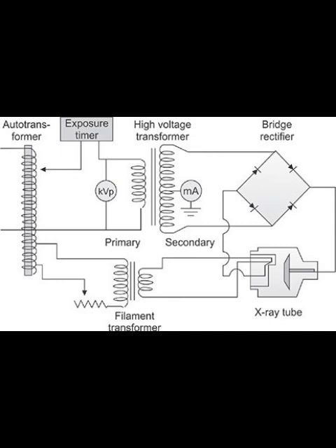It is. Voltage ripple is basically the fluctuation, the variation in the voltage output after rectification. Even with three-phase power and full-wave rectification, the DC voltage isn't perfectly flat. There are still small dips between the peaks of those pulses. Like ripples on water. Exactly like ripples on water. And just like you want smooth water, you want smooth voltage. A lower ripple means the voltage is more consistent, closer to a flat line.